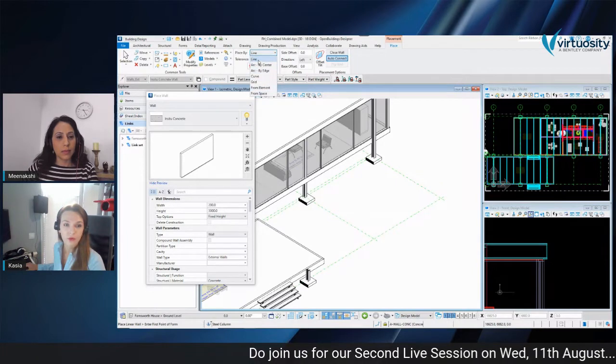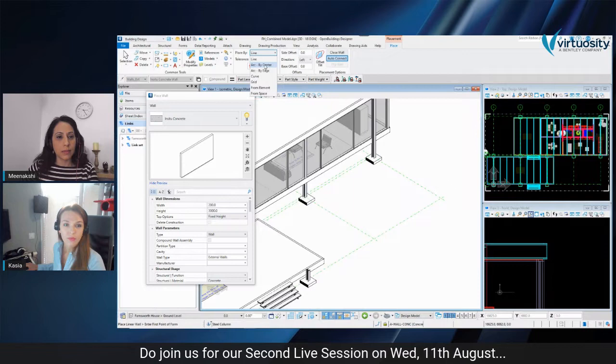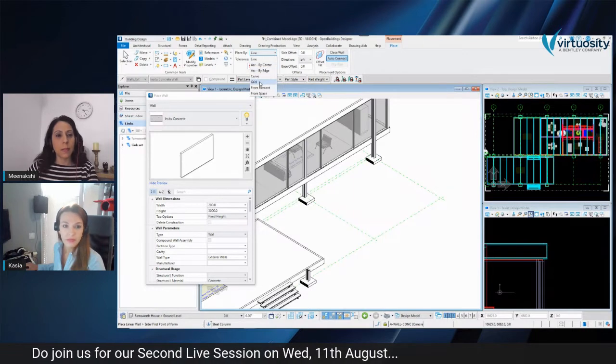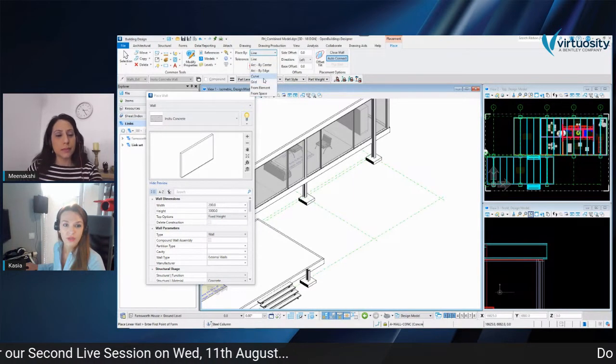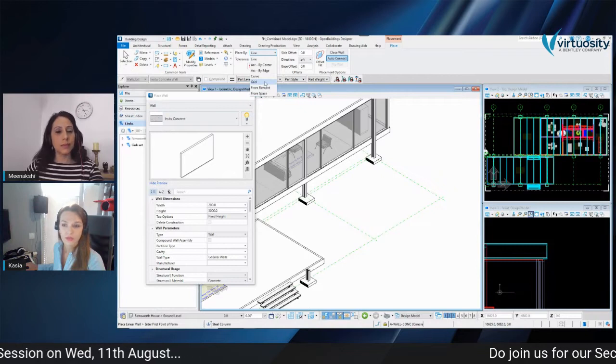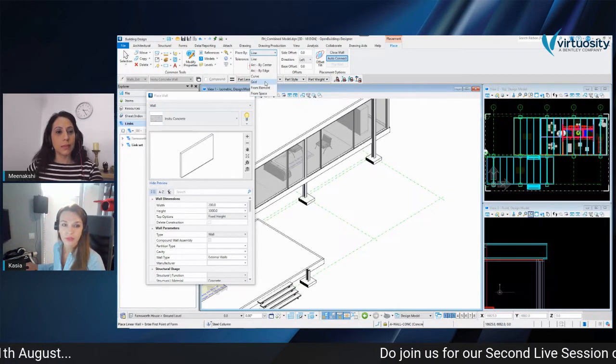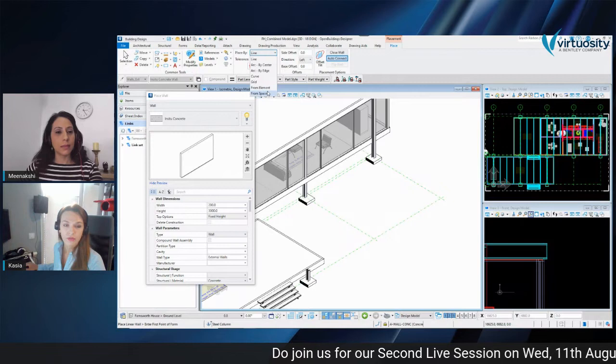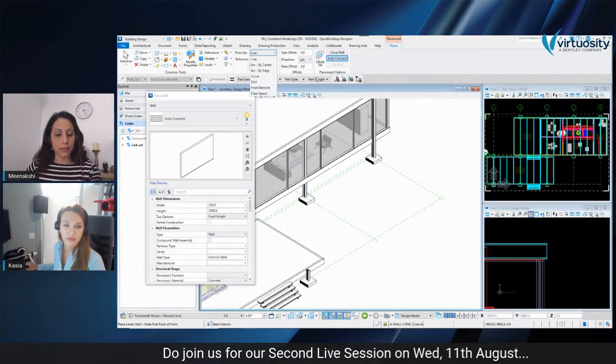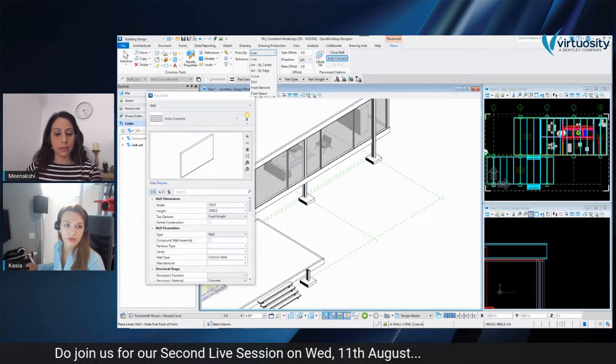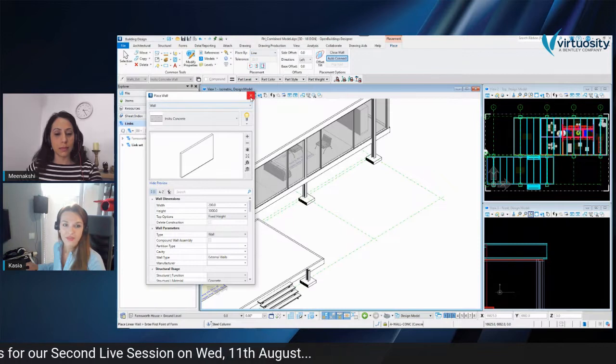So we can place the wall by line, but also by arc, curve, or grid, as I mentioned. So just using the grid, the structural grid for the building that we set, and then from element or from architectural space that we set in the architectural tab. So that's the general idea.